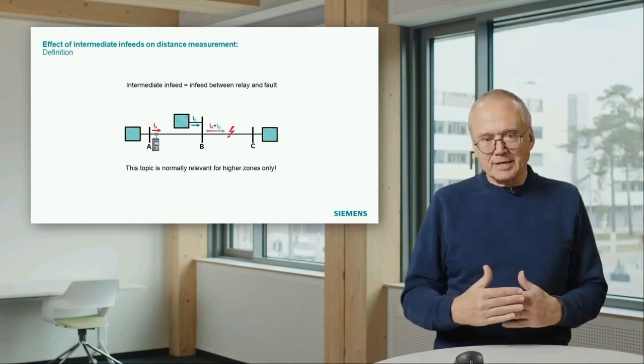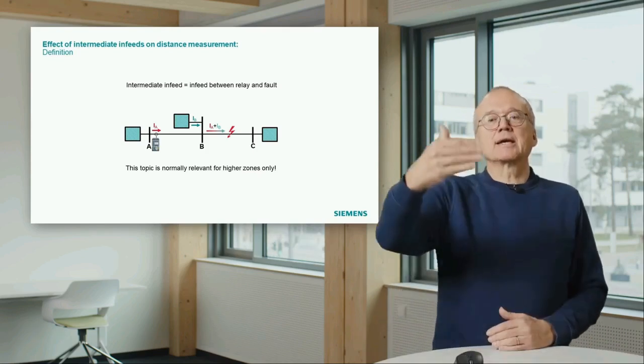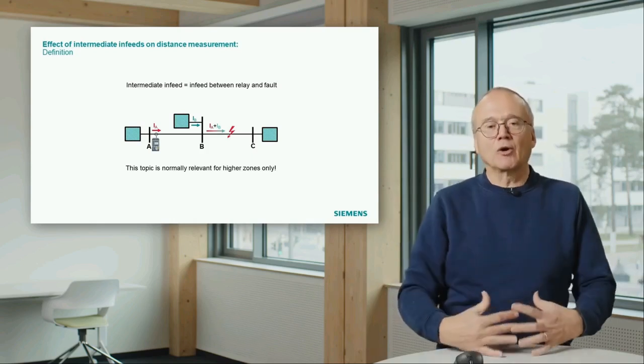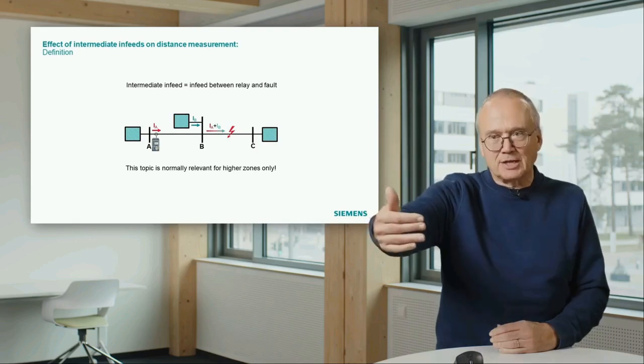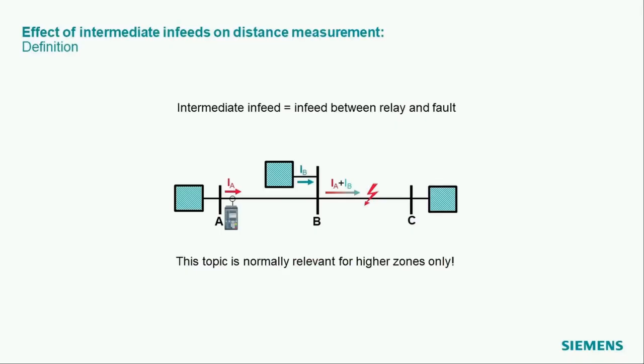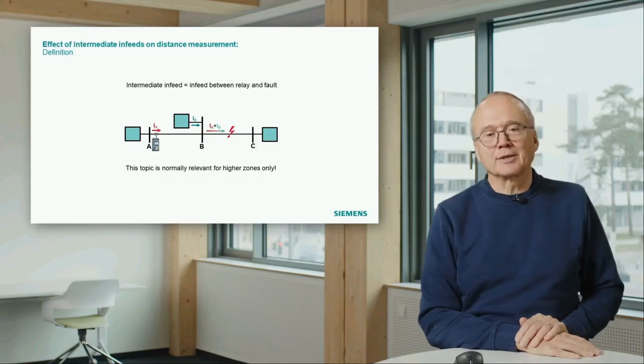That means the case where we measure into the next line, not into our own line, but beyond a substation into the next line, which is normally required for the backup case. And if we do that, we typically have the situation illustrated in this drawing.